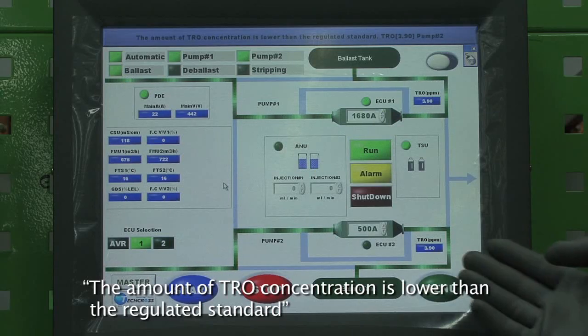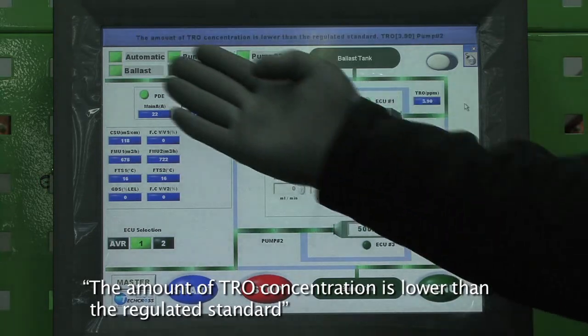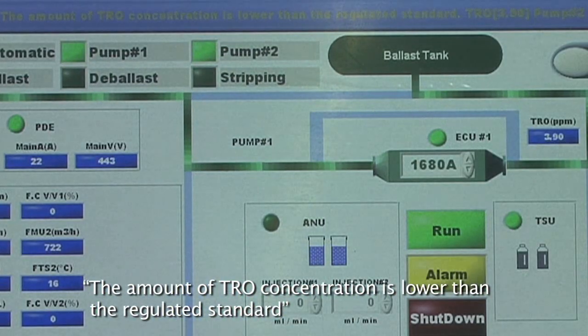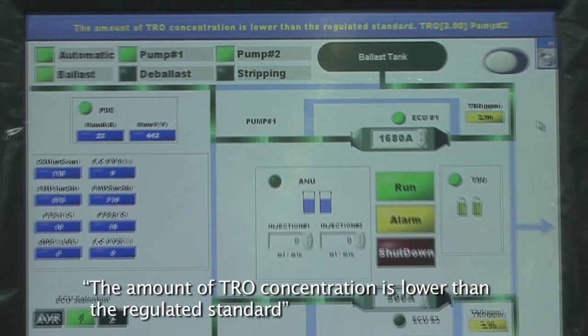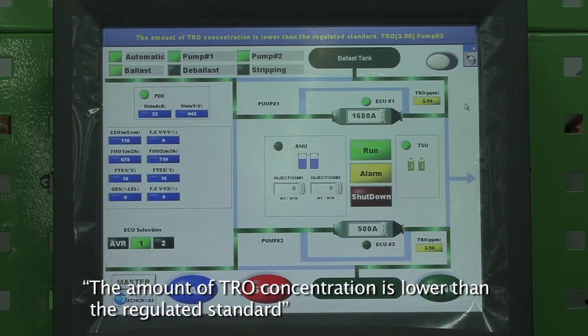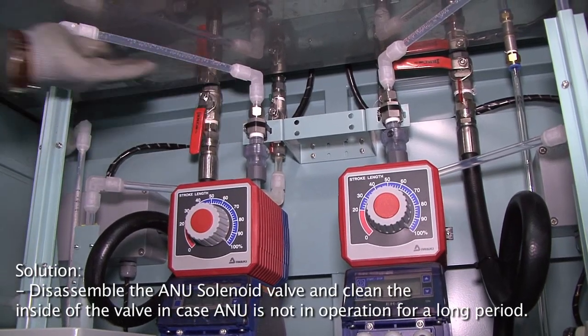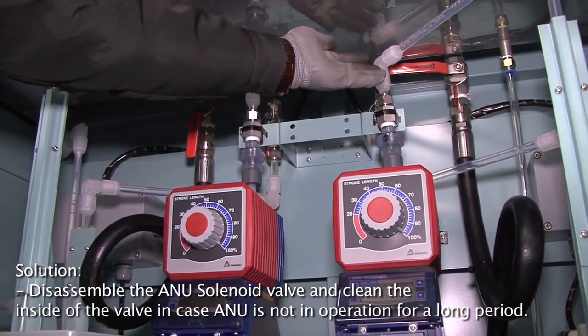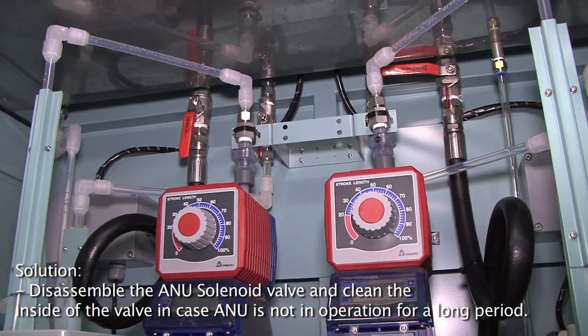Problem. ECS shuts down 10 minutes after alarm message, The amount of TRO concentration is lower than the regulated standard, appears. Reason. When discharged neutralizing solution is not injected to the pipe properly during deballasting operation. When outlet pipe of ANU is clogged up. Solution. Disassemble the ANU solenoid valve and clean the inside of the valve in case ANU is not in operation for a long period.